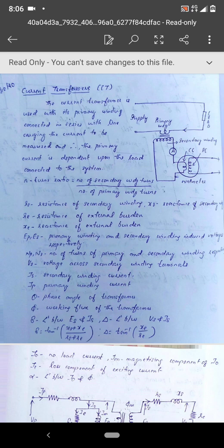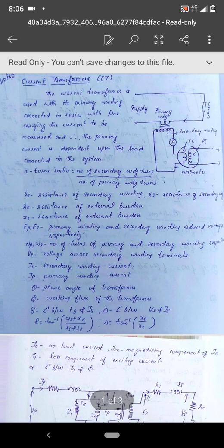The main thing is that the operating personnel is very close to the measuring instrument, and where the measuring instrument is measuring very high currents or voltages, that also brings into picture the safety issue. So that is one reason why we are preferring instrument transformers. There are a few more reasons, especially the division of current in shunts is not equal, and that depends on the ratio of R by X in the case of AC circuits, not like DC circuits. So there are so many reasons for that.